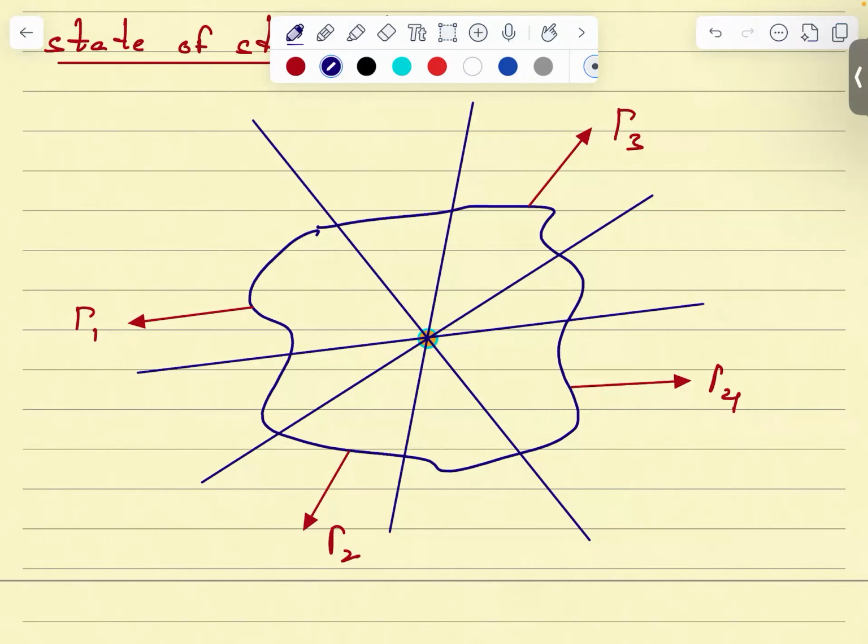No, sir. So for that, what we are going to do is find out where the maximum normal stress and where the maximum shear stress occur. Then we are going to name those planes as principal planes. Whatever plane in which the maximum normal stress acts, those planes are called maximum principal planes. Similarly, wherever you have maximum shear stress, we'll call those planes maximum shear planes. So based on that, we are trying to find out how the failure is going to happen.